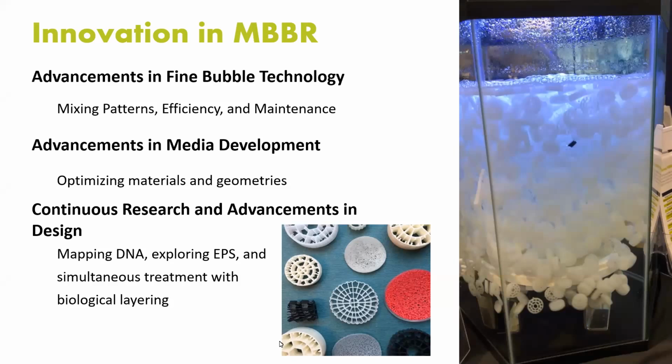There's also been a lot of advancements in fine bubble technology. We have PTFE now, we have more durable diffusers, so maintenance issues aren't an issue like they were in the past. We're able to optimize mixing patterns and efficiency and even maintenance.